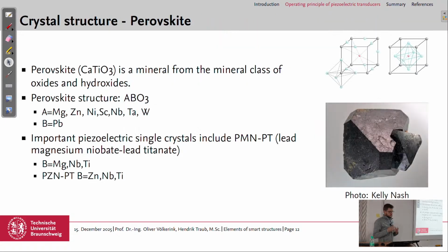The crystal structure of this piezoceramic material is a perovskite structure. It's a mineral class of oxides and hydroxides, and the perovskite structure has three different atoms or elements, A, B, and oxide. A could be magnesium, zinc, scandium, niobium, and so on, and B is, in our case, lead, or most of the time lead.